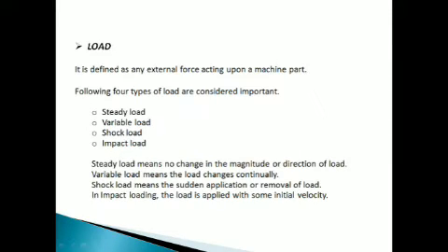Load. It is defined as any external force acting upon a machine part. Following four types of loads are important from the subject point of view. They are steady load, variable load, shock load, and impact load. Steady load is if a load acts on the body and it does not change in magnitude and direction, then it is called to be steady load.